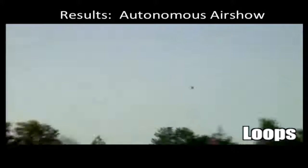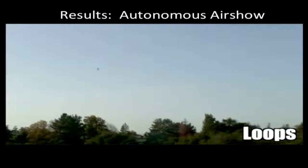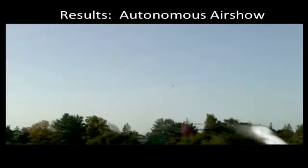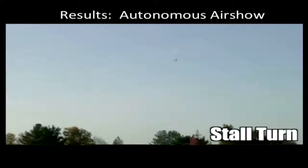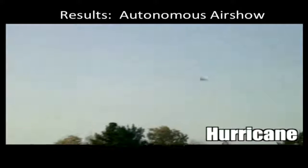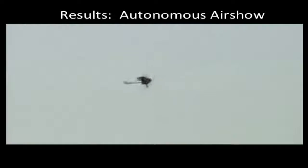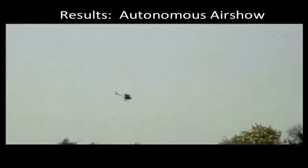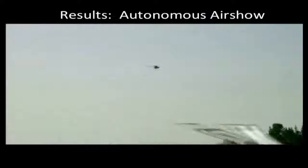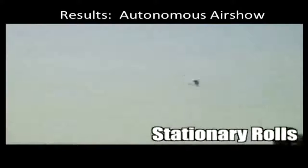Loop: if you do a loop and you want to show you're in control, you appear with the tail around at the top. Another stall turn. You can come out tail first from these stall turns. It's less stable, so you need to be more precise with your control, but you can do that. Hurricane is fast backward flying circles. Then some more inverted flight. Knife edge fall. Fall on the side of the helicopter so it doesn't have any control.